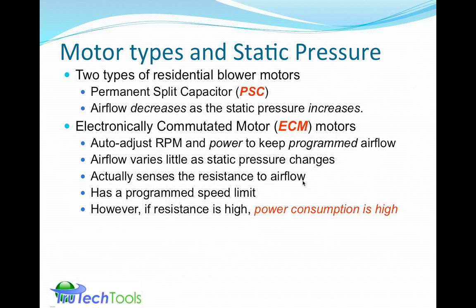But if the resistance grows and gets higher for the system, it will try to keep up at the sacrifice of power consumption. Usually these are installed to save energy, but if you're not careful and you have a situation where the static pressure is increasing, the power consumption may be very high and actually more than a PSC motor.